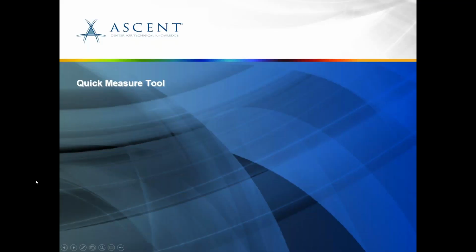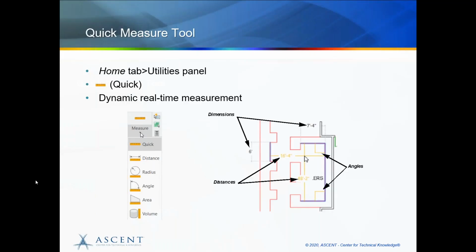So the quick measure tool, let's go over it quickly. The quick measure tool provides you with multiple measurements in real time. It is a quick and easy way of displaying the dimensions, distances, angles, and areas in a single command. As you select the tool, the cursor displays an infinite plus mark. And as you hover the cursor over some objects, all the appropriate measurements close to the cursor are displayed.